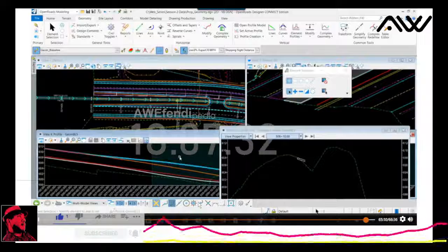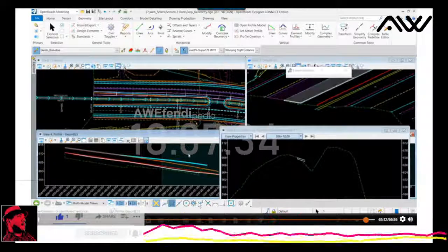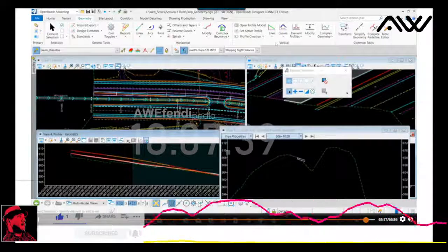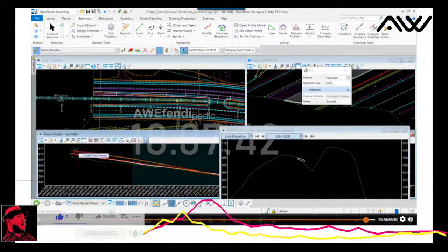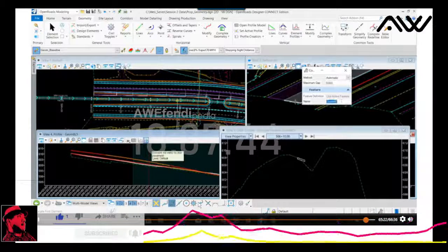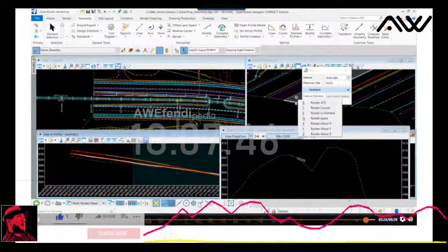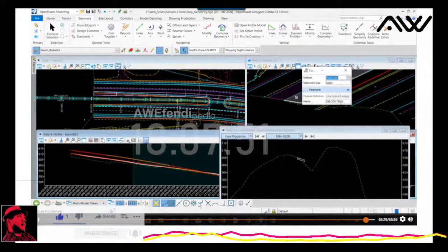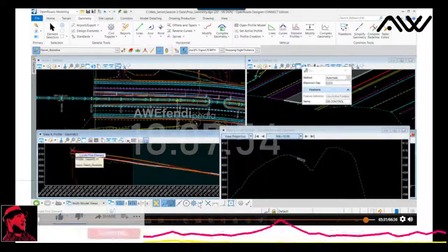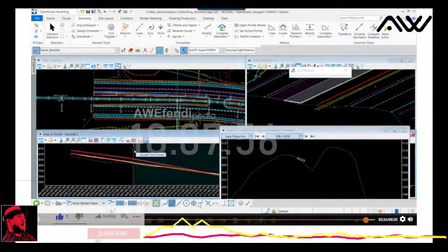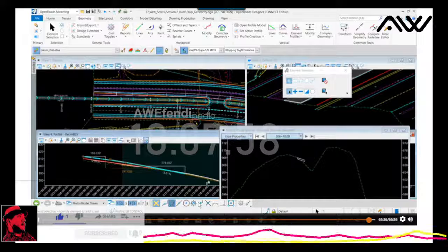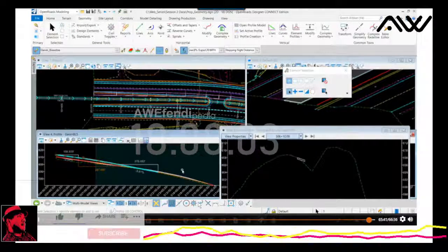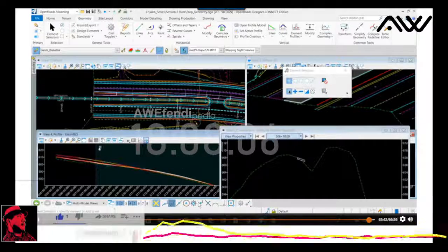I'm going to delete the graphical representation of the edge of pavement so you can see this more clearly. And I'll complex them together. And again, we will name this EB control. And again, it's just a matter now of selecting those elements. And there's the resulting control line. Okay? So through this process, I know we're about 5 minutes over, but I wanted to make sure I get that control line in there and show you how I'm accomplishing that.